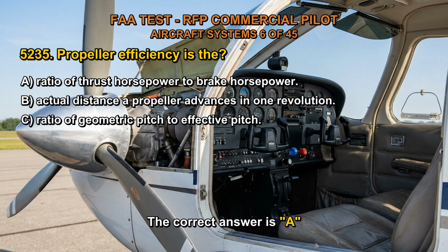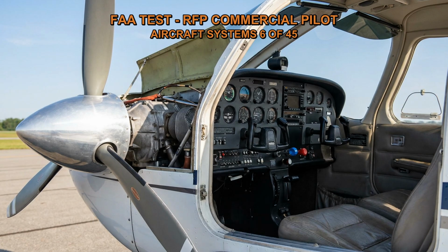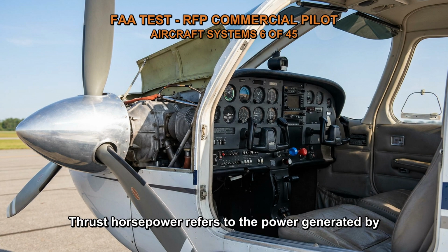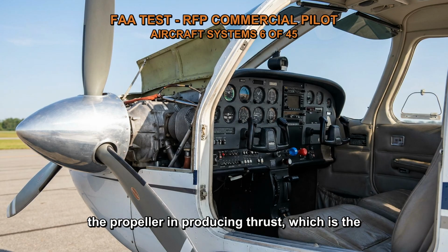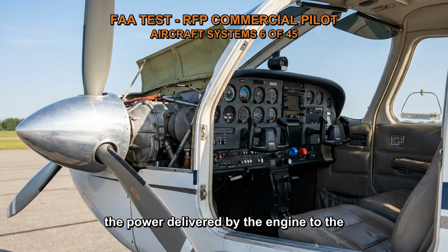The correct answer is A. Propeller efficiency is defined as the ratio of thrust horsepower to brake horsepower. Thrust horsepower refers to the power generated by the propeller in producing thrust, which is the force that moves the aircraft forward. Brake horsepower, on the other hand, refers to the power delivered by the engine to the propeller.